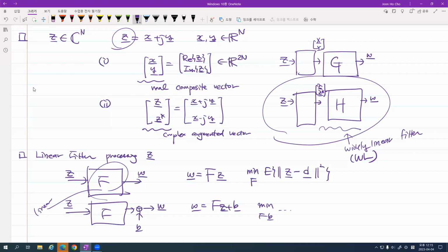That translates to proper complex Gaussian. However, man-made signals such as radar signals and some communication signals are often better modeled as improper complex signals when you find the complex baseband equivalent signal given the real bandpass signal. Got it? And that's why this approach sometimes, not always, becomes very important.